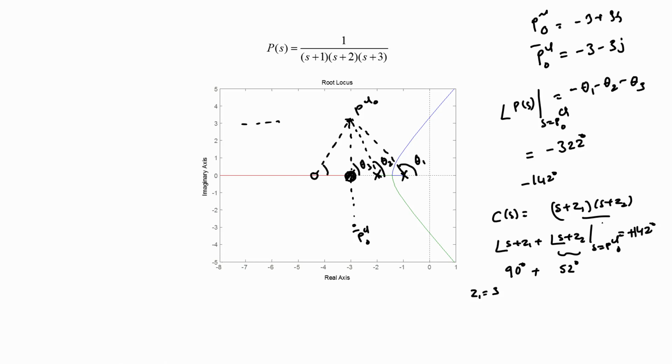So, I shall choose the denominator to be of the form S plus P the whole square, and I shall choose also to locate the point P at 30, or in other words, the pole of the controller is at S is equal to minus 30. Now, once again, this point S is equal to minus 30 where I have chosen to locate my controller pole is rather arbitrary.